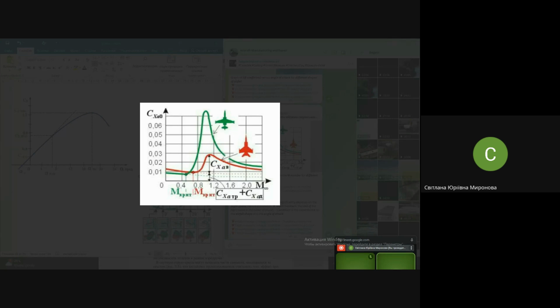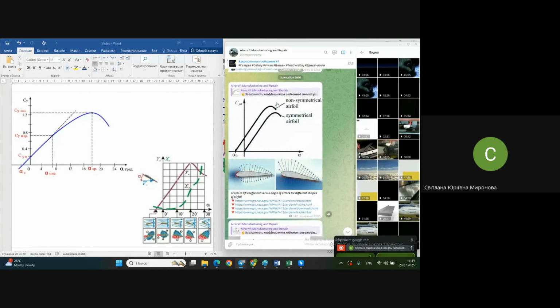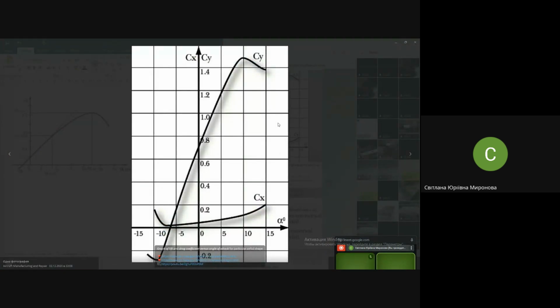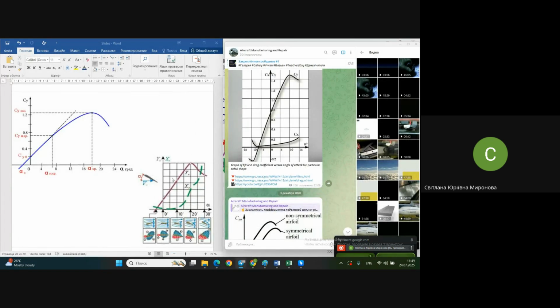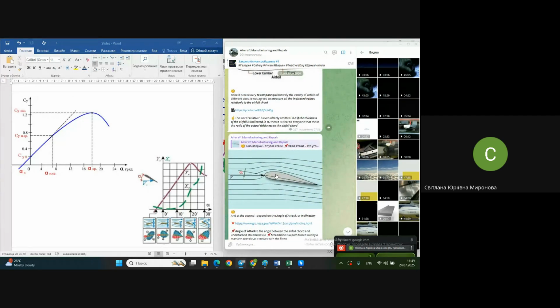But in general, you see, wait a second, where do you see it? Here. In general, you see the more angle of attack here, the more drag. Do pay attention, here it's not less angle of attack. It's like an anti-airfoil. Imagine the same airfoil rotated with the nose down, with the trailing edge higher than the leading edge.